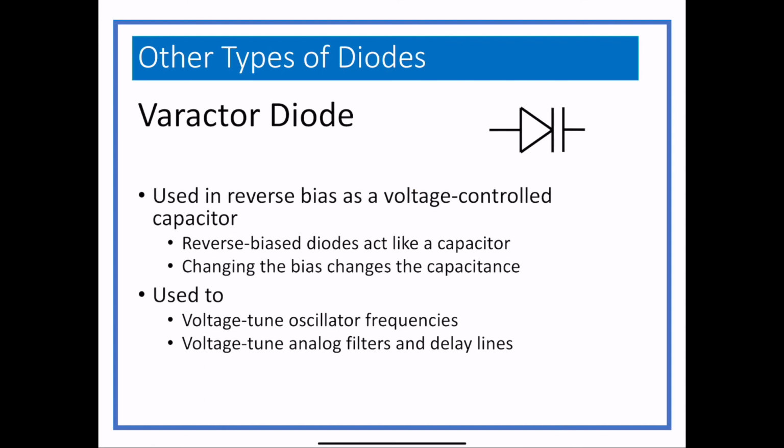And when you are using LTspice, I think when you type in V for voltage, you get this first. You have to type VO for a voltage source. This is what pops up when you're trying to find the voltage source.